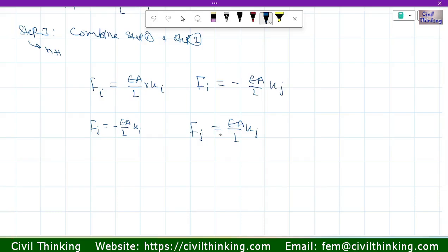Remember, I have told you, when we do the meshing, we don't talk about F equal to Kx. Okay, because after meshing, what is going to happen? After meshing, we will get elements and nodes. So it is going to be F matrix is equal to stiffness matrix times X matrix. And we will understand this, because we got multiple values of F. If it was a single F, what would we do? We couldn't do anything, right?